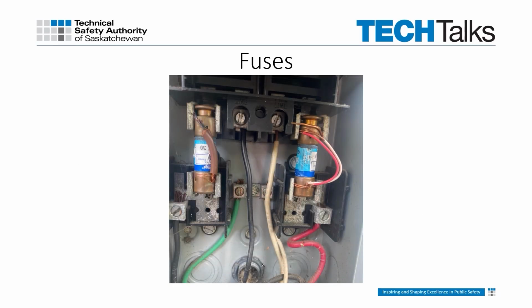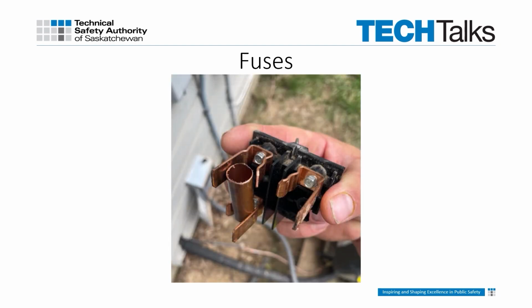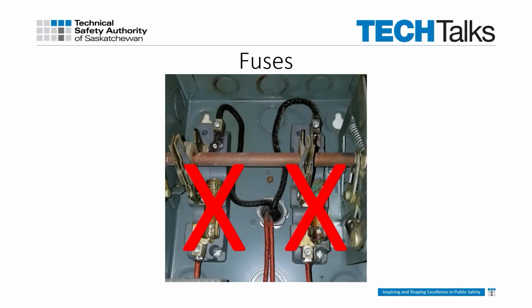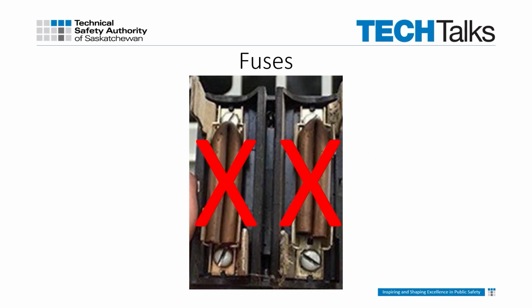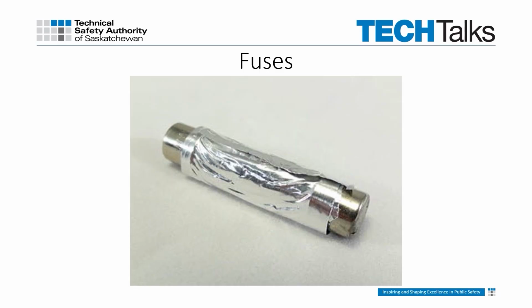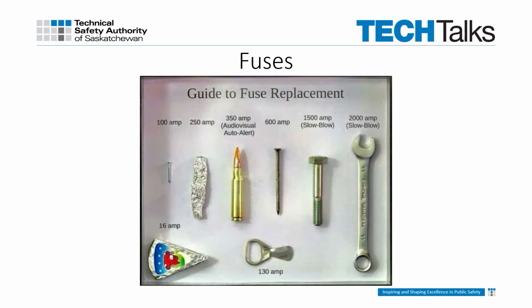Clearly, there's a lot of thought and coordination to selection of fuses for their ratings and characteristics, and changing any one of those factors can greatly impact the circuit and equipment. Never use a dummy fuse, copper slug, length of wire, or anything else as a permanent fuse substitute, or even as an interim fix until the exact match fuses arrive. Use of fuse substitutes can cause non-operation and equipment damage. Of equal, if not greater concern, would be an improper operation, leading to a violent failure, creating arc blast and molten metal spraying about.